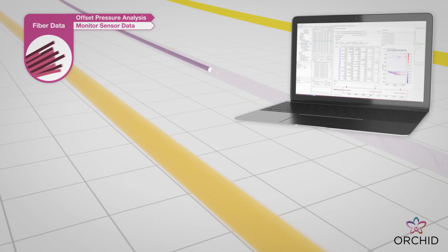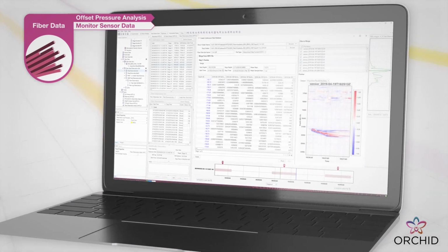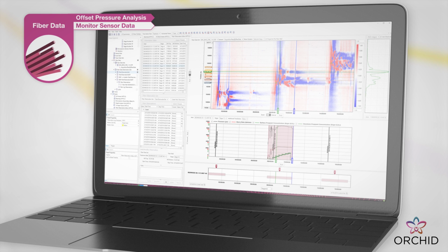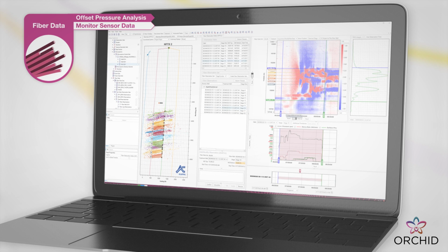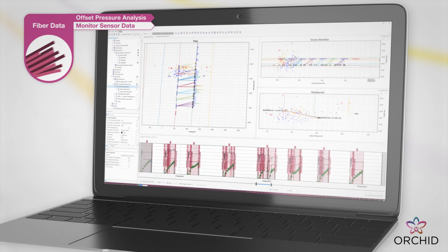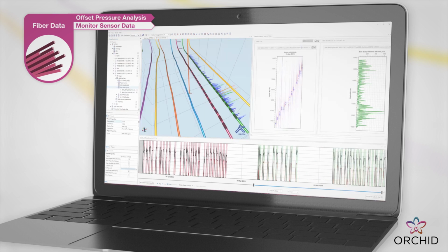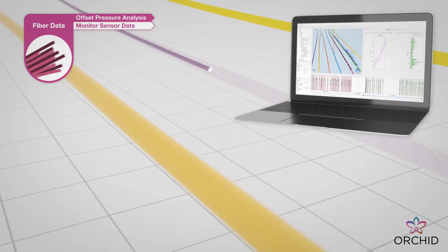More recent, easier access to fiber data allows operators to add another detailed level of definition to their fracture mapping. Smartly creating a continuous data set from any type of input data format, Orchid displays waterfall plots that are easily navigable and can be interpreted to pick or QC frac hits, fracture, or stage corridors. Discovering how many fractures intersect the fiber wellbore, the fracture azimuth, as well as cluster efficiency, are all important results that can be derived from DAS and/or DTS data.